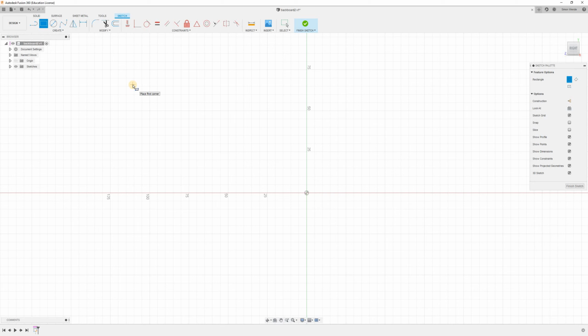Also next to my cursor there's a rectangle icon, and I'm going to hover over the axis here, click with my left mouse button, release the button, move my cursor, and click again. Alright, you can see that I'm still in the rectangle tool environment, so I need to click Escape and I exit that.